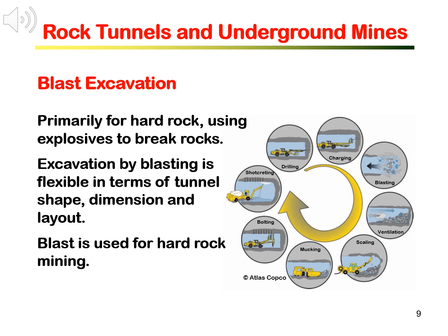The typical drill and blast excavation cycle is illustrated on the right. Excavation by blasting is flexible in terms of tunnel shapes, dimensions, and the layout. Blast is also used for hard rock mining.